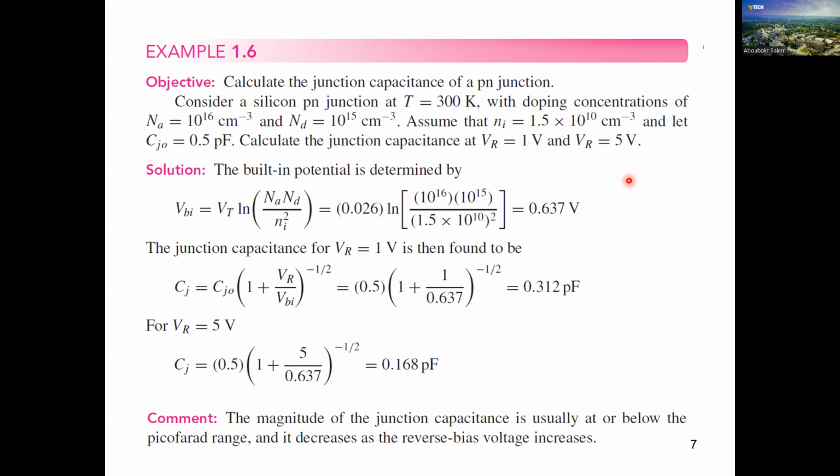So simply, firstly, we calculate the barrier voltage Vbi using our relation. We calculated this before. So for this material, with this concentration, the barrier volt is 0.637. And we mentioned before, it varies according to the material. It can be from 0.4 to 0.8, something like that. Can be a bit higher, a bit lower. So this is the range of the barrier volt for semiconductor materials.